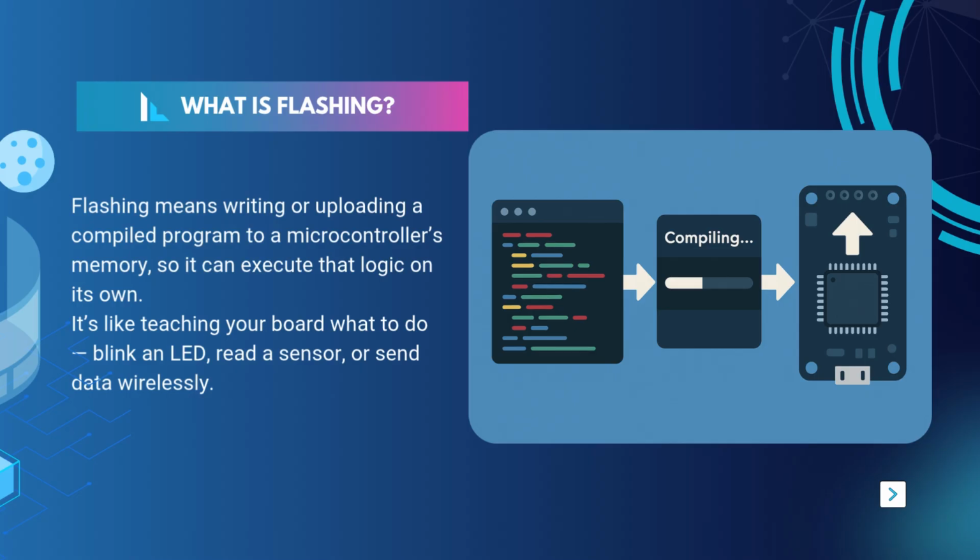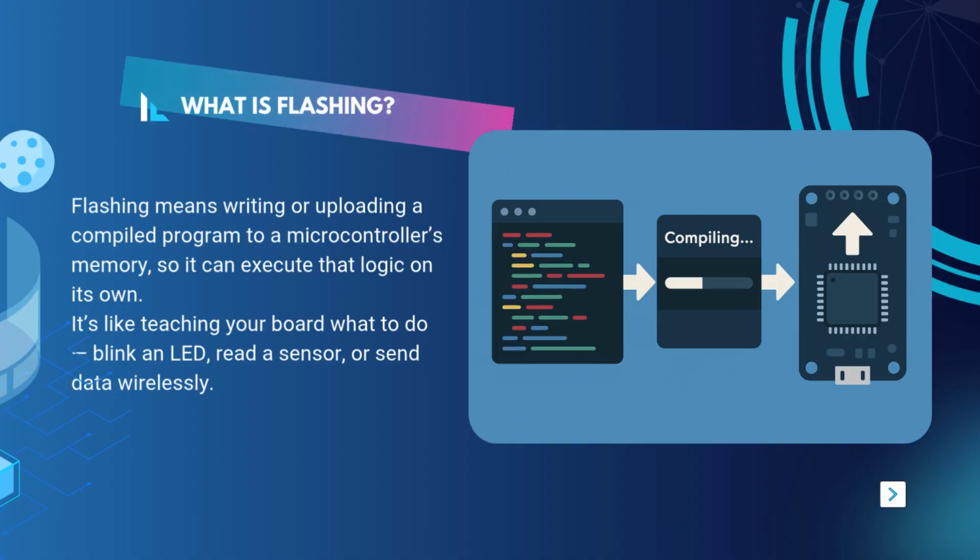You write the code on your PC, compile it, and transfer it to your board's memory via USB or another communication interface. Every microcontroller has a small bootloader, a special piece of code that allows it to receive firmware updates over standard interfaces. Without this, you'd need specialized equipment to program it. Understanding this is key, because if flashing fails, it often means there's a problem with either this bootloader or how your development environment is communicating with it.